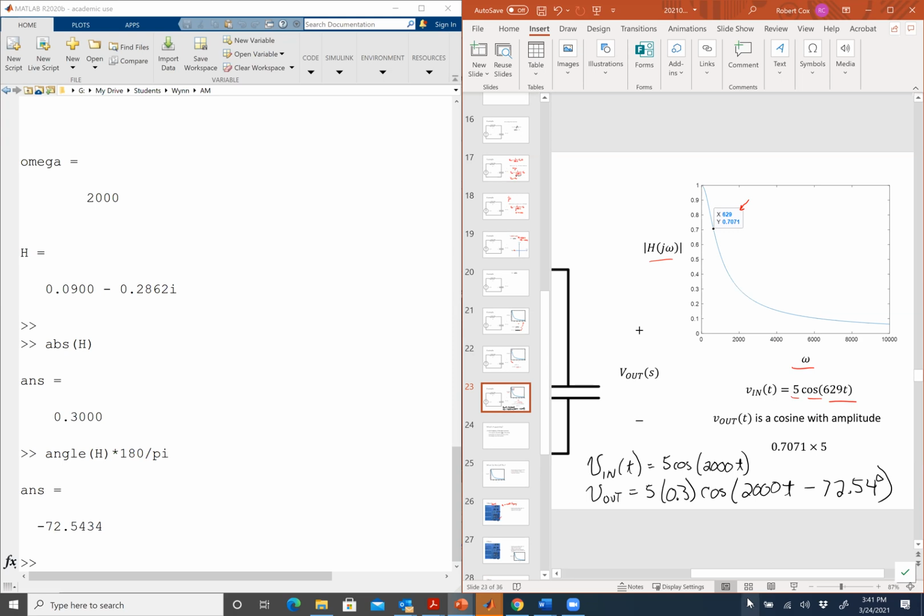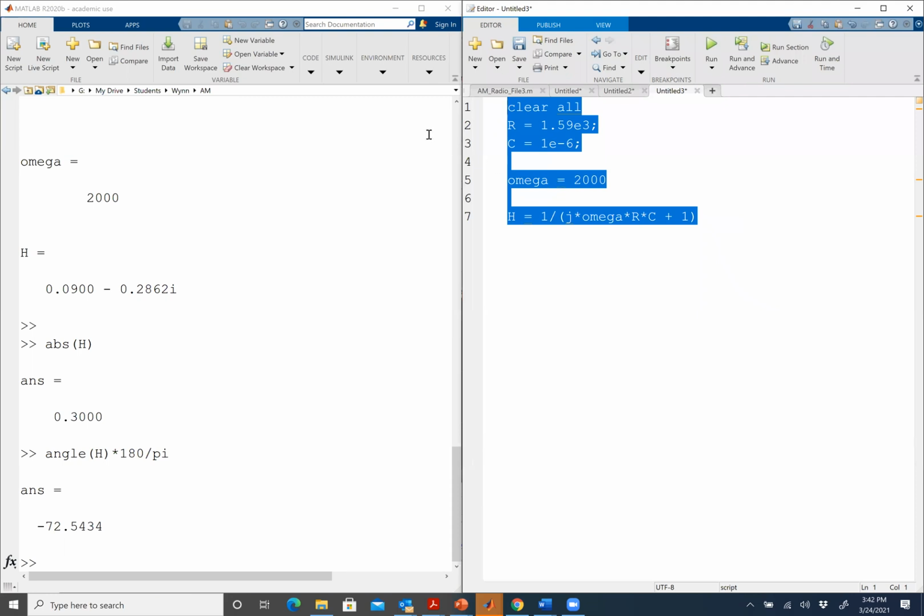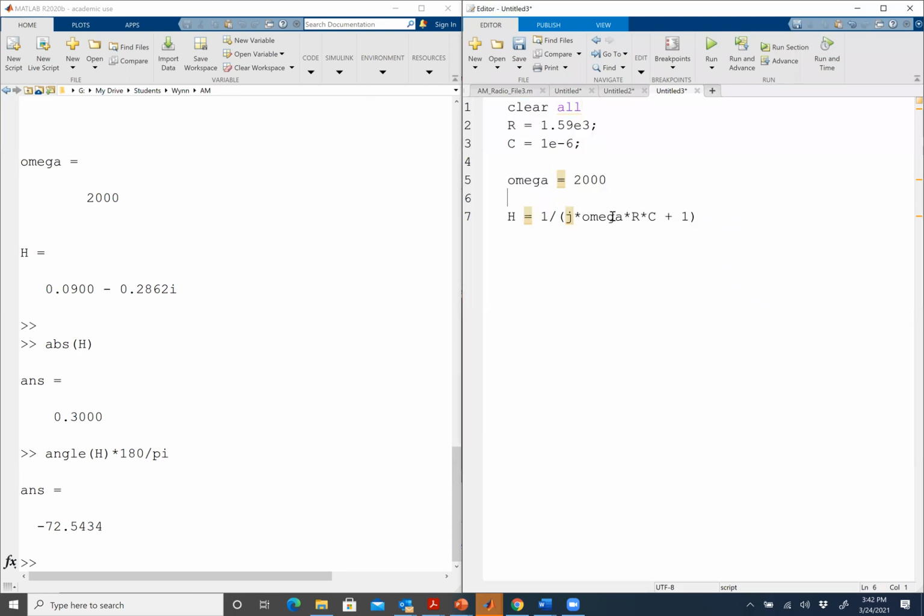And what we often do, and what we're not doing on this homework, just to be clear, homework 8, which is due Friday, you're not making these graphs, right? I'm going to give you, or I gave you in that homework, all the frequencies. So basically what you need to do is evaluate the transfer function like this. Everywhere you see an S, you plug in j omega.